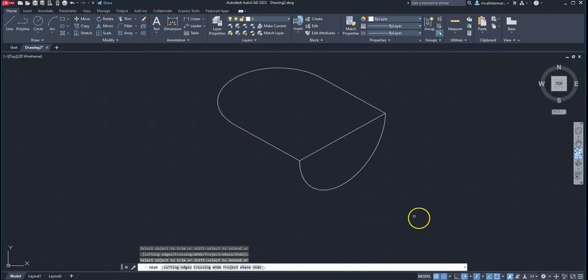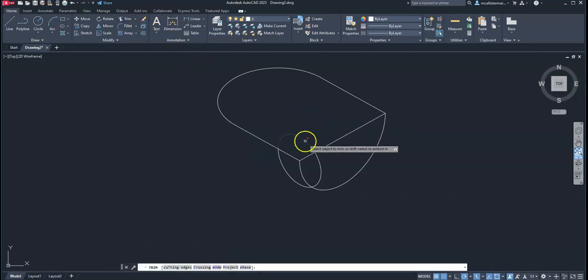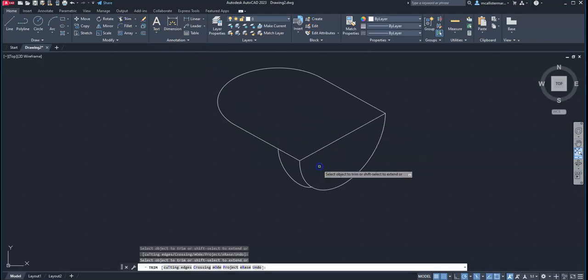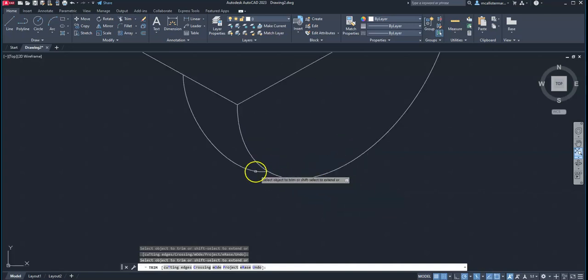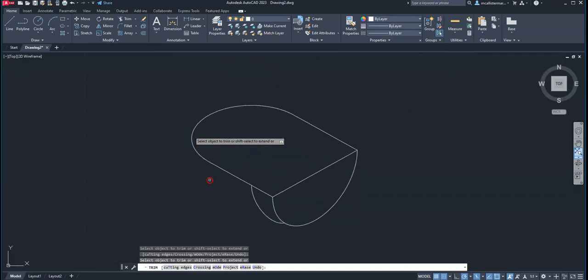We could also flip to isoplane left, and I'm going to type ellipse again and hit I and hit enter, and maybe I could get myself some kind of an ellipse down through here, just to give you an idea of everything that we can do in AutoCAD. Grab that trim command. Going to trim off here on the side. We could put a little line in here if we used our tangent constraint, cut some things off. A lot of neat things you can do with IsoCircles.